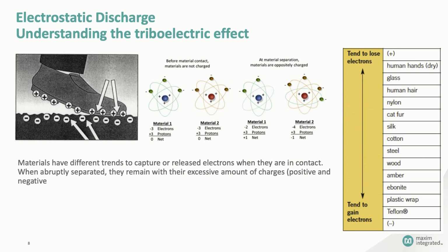So, let's get this straight. Electrostatic discharge at levels far too low to actually cause a spark can damage or destroy MOS transistors. And you can't get away from static electricity due to the triboelectric effect that's all around us. So, what can we do? Well, as it turns out, there's actually quite a lot that we can do.